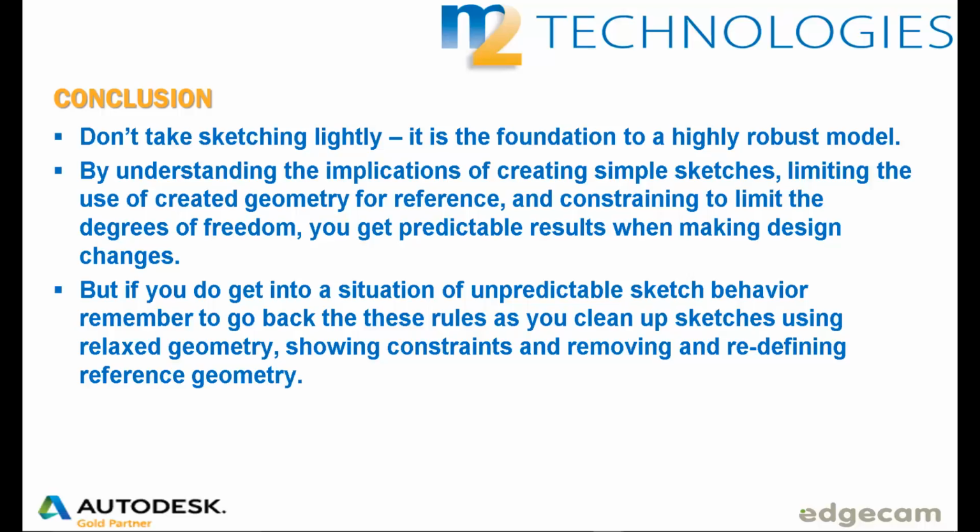So let's conclude here. First off, using sketches smartly in your design is not something you should take lightly. It really is the cornerstone to your design changes later. Having good, solid sketches always creates highly robust models. So whenever you can, planning out where you place your constraints and what features you're using to constrain from really makes a difference, especially during editing.